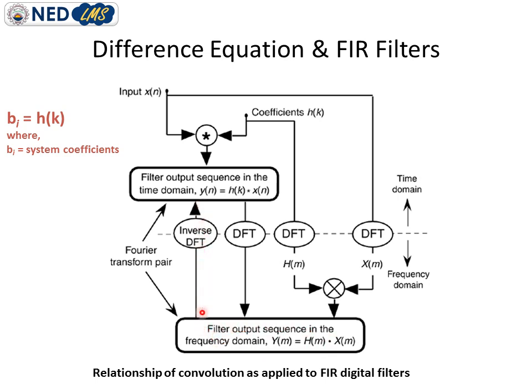So here is the conversion from time domain to frequency domain. If we take the inverse FFT of this frequency domain version, we will transform back to the time domain, which is the same as the result of the convolution of these two signals, the input signal and the impulse response.